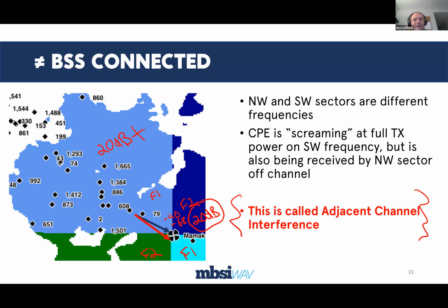When you have systems that do not have GPS sync, this problem is exacerbated even more, because I could have a situation where F1 is in receive and F2 is transmitting at the same time, and then I've got this noise coming from the system all added together, and it makes for a very chaotic and almost unmeasurable environment, except that you see crappy data rate.